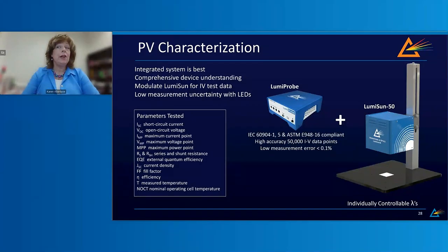So for complete characterization of a solar cell, solar simulators are often used with PV characterization modules. Integrated systems offer ease of setup and measurement, for example, pairing our LumiProbe and LumiSun, though the LumiProbe is actually compatible with LabVIEW, and you can use it with other solar simulators as well. LumiProbe in particular exceeds IEC and ASTM standards. It's also capable of tracking the temperature of the PV cell and providing correction.